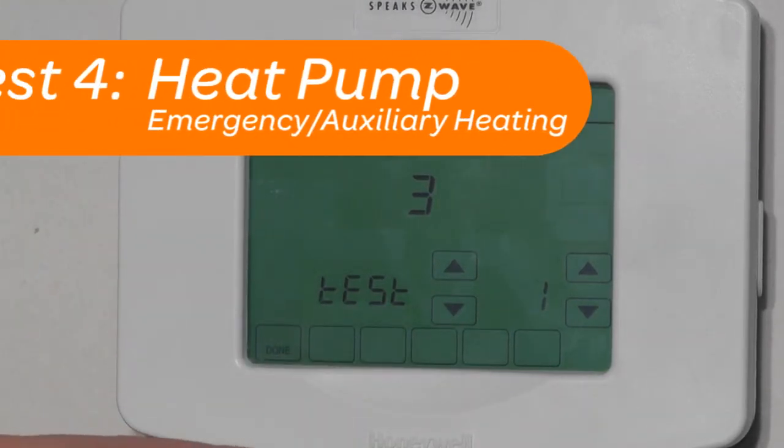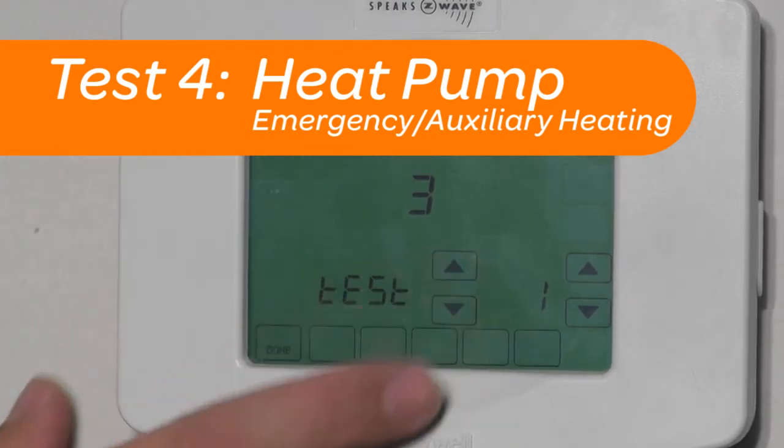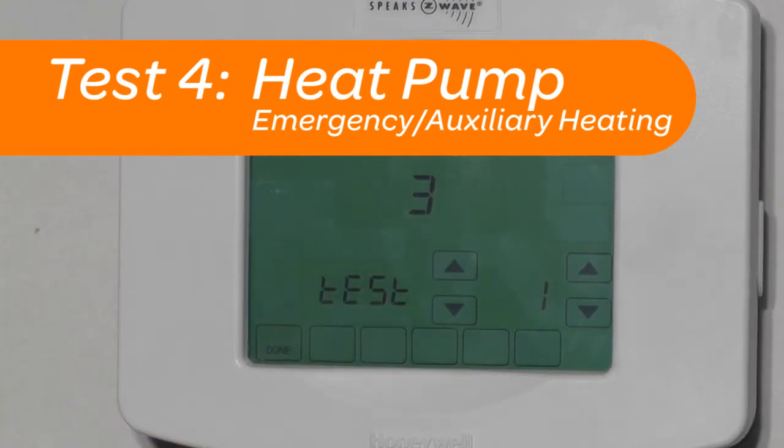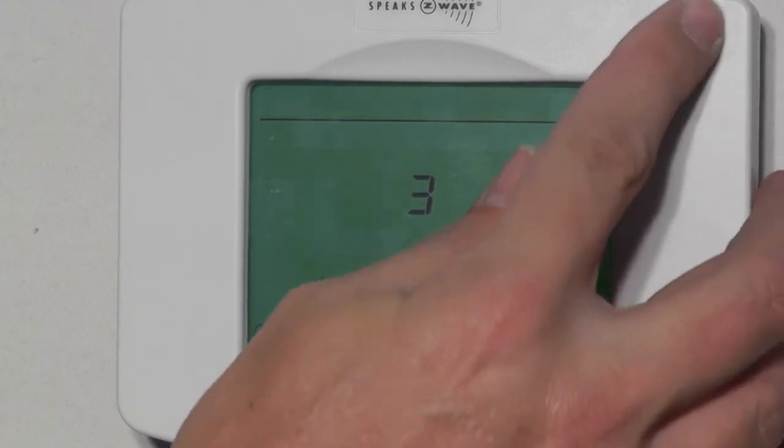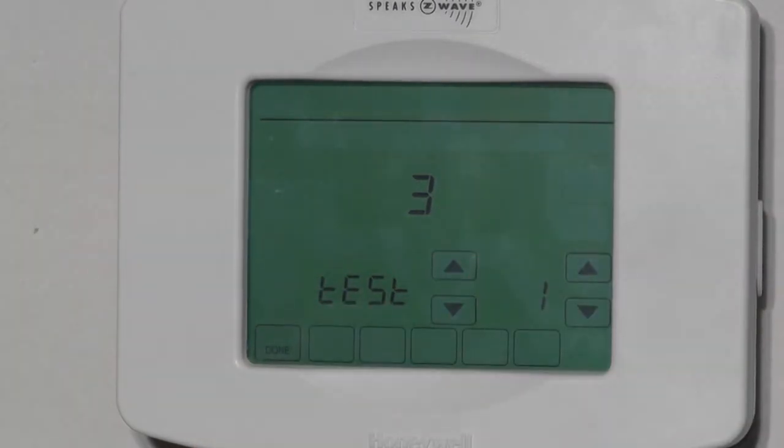Test 4 is for a heat pump with emergency heating. While not displayed here, the system would be tested using the same procedures as for tests 1 through 3. The only difference for test 4 is that a red LED would light up on the right-hand corner of the thermostat indicating emergency heating is on.